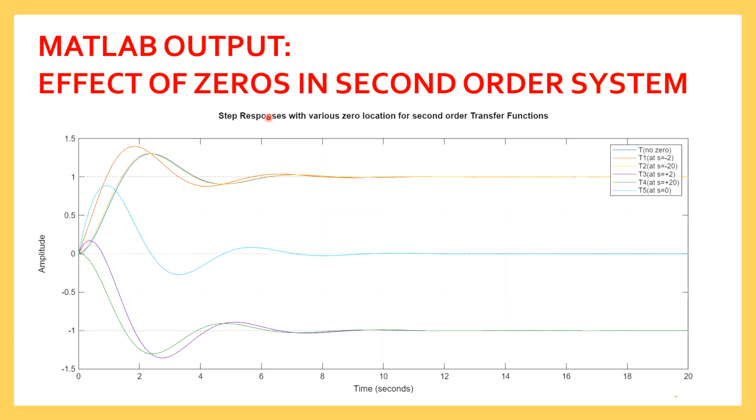The same applies for the second order system, but it is an underdamped system, so the response will have an underdamped shape and then it reaches the final value. Here also we can see that the initial value is 1 and the final value is -1.